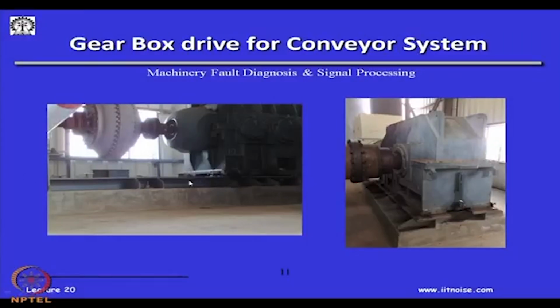So, at this location in fact, this was about 100 meters from the ground on a platform made out of concrete, because the conveyors were coming out from large ships and they are high over the ground, and obviously if this floor is not level, this system could have a misalignment.